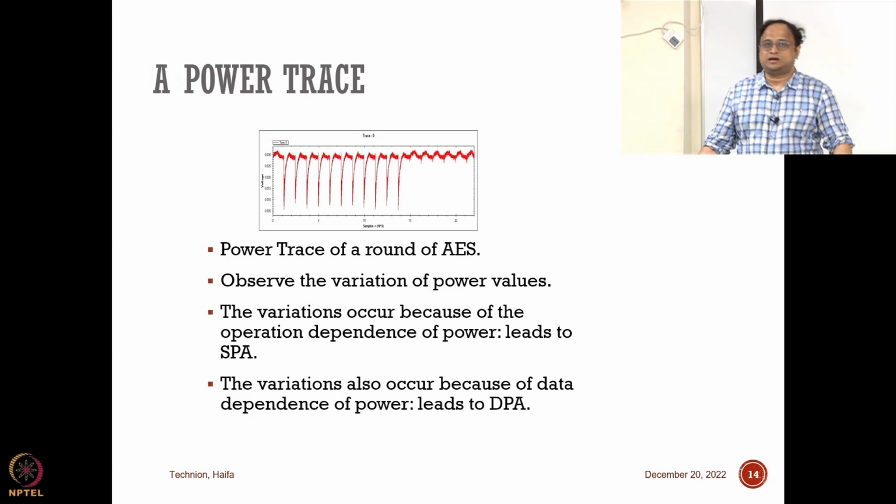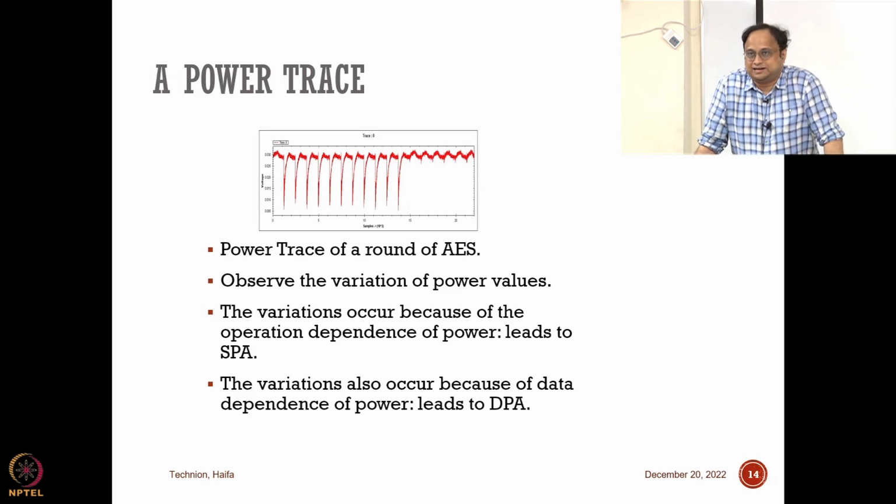So AES-128, I told you that it has 10 rounds of operation. Can you see those 10 rounds in the power trace? If you count, there are 10 jumps, very periodic, right? So you can practically read and note them when observing this power trace.